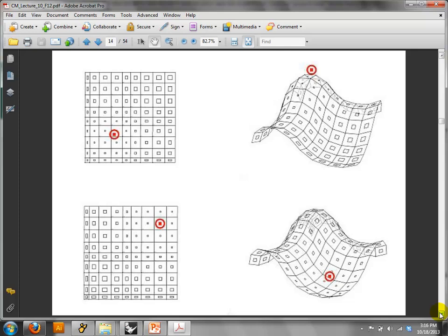The displacement's fine, but this is a flat sheet of points, and I can use the attractor logic and say, okay, where it's near a point, reduce the z, or where it's near a point, increase the z. And that's just a very, very simple way of thinking about how to disturb the surface. Again, you could be designing a park and you want there to be mounds wherever there's a tree. The positions of the trees are going to change, or are going to be distributed by some other logic. This is going to help you shape your topo lickety-split. And as you change those things in the project, the topo changes automatically.